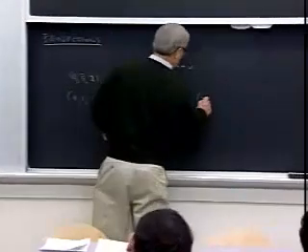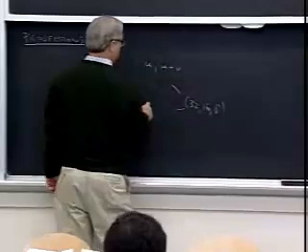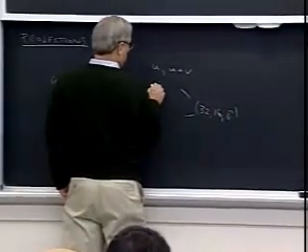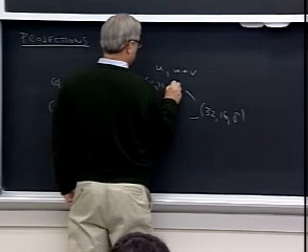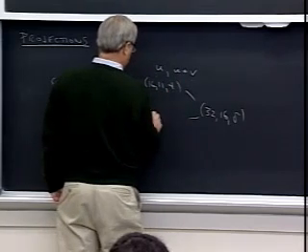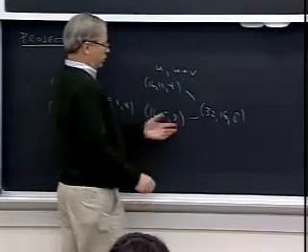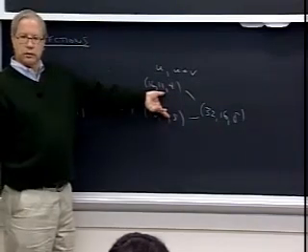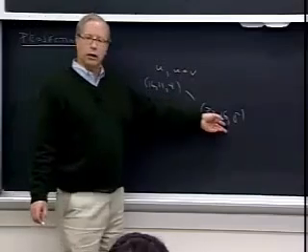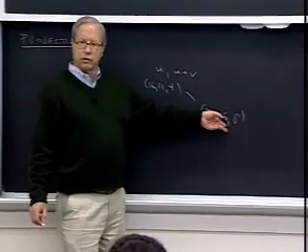But for instance, if we have the 32.16.8 code, what is that made up of? That's made up from the 16.11.4 code and the 16.5.8 code. And so we can see the dimension of the central state space here is going to be 6. We're going to get a 64-state trellis for this code, at least just measuring the size of the central state space.